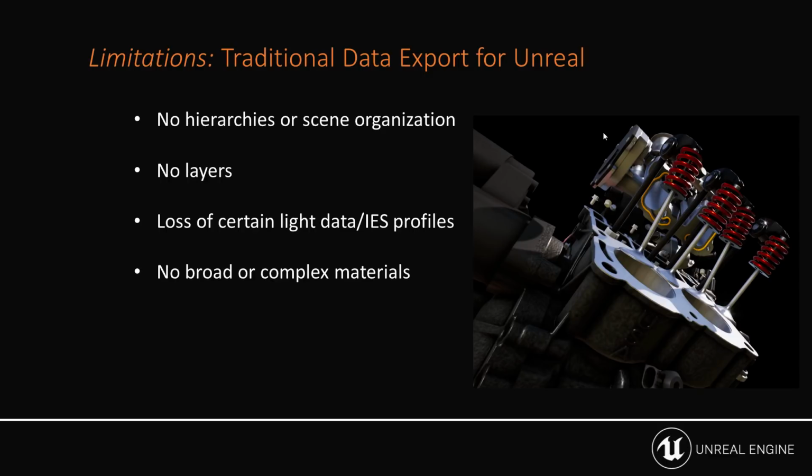So, third-party plugin data. This could be an example where an application like 3ds Max supports it and Unreal supports it, but the FBX format in between does not. So we lose that data in translation, literally lost in translation of moving the data back and forth. And of course, if you're working with things like instances, formats like FBX will lose those, and you've lost out on your instances coming over.